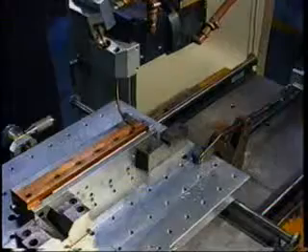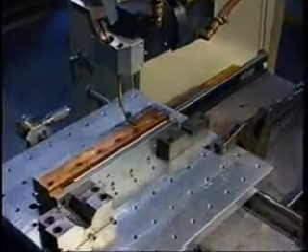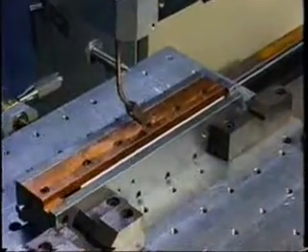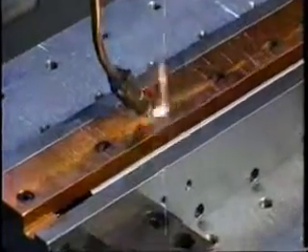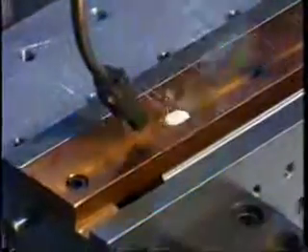Most laser welds require no filler metal, although filler metals can be used if desired. Inert shielding gases are normally employed, usually argon, helium, or a mixture of the two. Welding speeds are usually much higher than other welding processes, thus limiting heat-affected zone size and workpiece distortion. In addition, because of the intense, precisely focused heat, welds can be quite deep. Also, welds can be made in confined regions and between dissimilar metals.